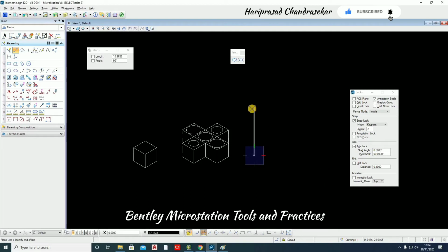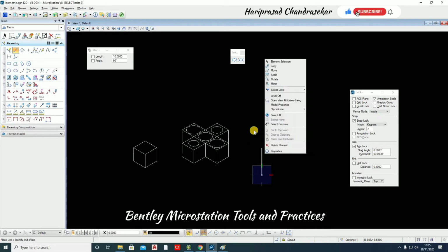Now you will be having these things. Axis in the sense it will go only horizontally or vertically. This is similar to ortho mode. So now if you want to draw a line here, enter, click outside, enter, click outside. So I'm just drawing a 10.